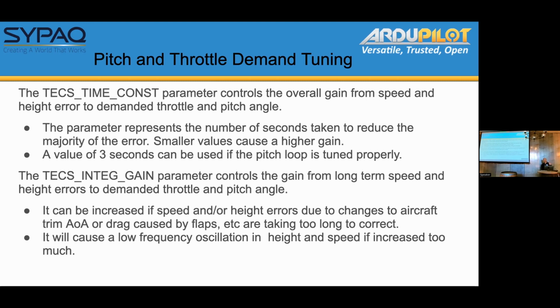But the other important attribute is you can set up a radius so that you end up with a nice shallow bank angle of about 15, 20 degrees. So you're not biasing the results with drag due to turn in the aircraft. And the other advantage is that when you set a height change in guided mode, the TECS gets a step change in height.